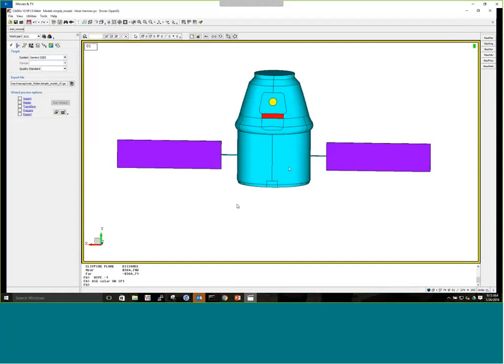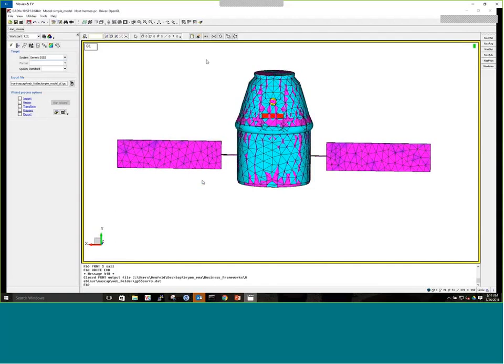And so now we have a geometry that's been parsed by regions and assigned materials to those regions. So you have an import, a defeature, and then an assignment by region of materials. And now we're ready to make our NASCAP simulation object. And with this third button here, you just define the set that has all the surfaces of your object, and then set a destination file name, and lastly you control the resolution of the mesh. The smaller number here gives you a finer resolution. And so once you select all of that, there's your mesh for the model.